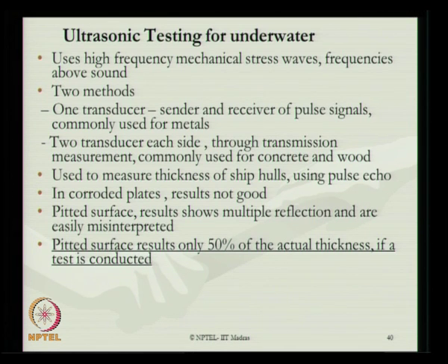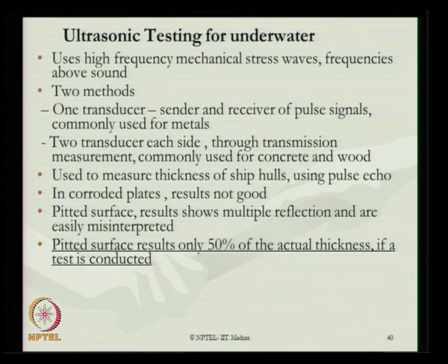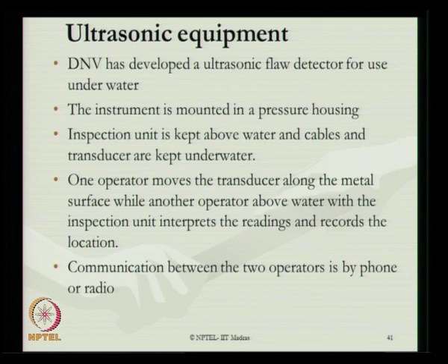This technique is used to measure the thickness of ship hulls using the pulse echo method. In corroded plates, when you apply this kind of method, the results are not encouraging, as you see from the literature. On a pitted surface, the results show multiple reflections and are therefore wrongly interpreted. The pitted surface gives only 50% of the actual thickness, and therefore this method is not effective for pitted surfaces, as you see from the literature.